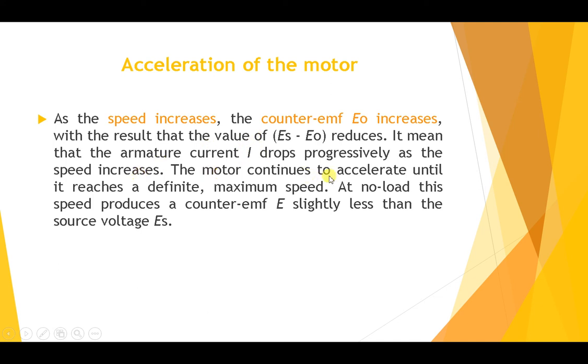The motor continues to accelerate until it reaches a definite maximum speed. At no load, this speed produces a counter EMF E slightly less than the source voltage ES.